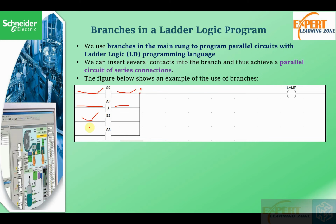And similarly for S2 when it is true, and for S3 when it is true. So this condition makes them operate in parallel, and it makes them become branches, because logic can either flow through S0 to the lamp, or through S1 to the lamp, or through S2 to the lamp, or through S3 to the lamp.